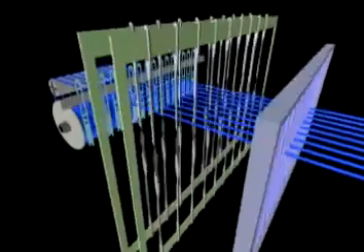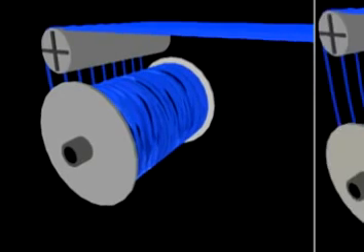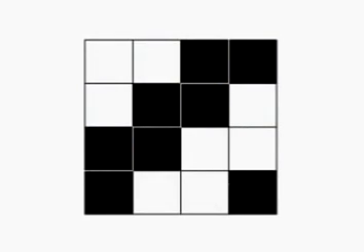In addition, the loom backrest or whip roll setting can affect the height of a twill as well. A low backrest will give a softer or lower height, while a high backrest will give a pronounced or higher twill ridge. The graph shows that a 2x2 twill repeats on 4 ends and 4 picks. Each warp yarn rises over 2 picks and then sinks under 2 picks. The 2x2 twill is a balanced twill.